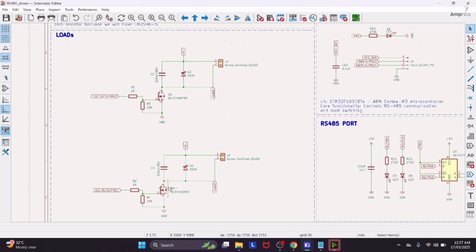And if I talk about the protection, so instead of the given diodes we have used the SS34 Schottky diode. It has almost the same configuration, so we can use this also. Why did I use this one? Because it is very popular and easy to find in the market, so for that reason I have included it.